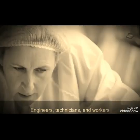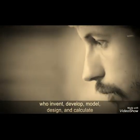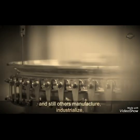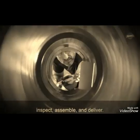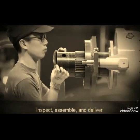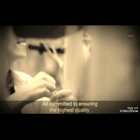The manufacturing of 3D woven carbon fiber composites starts with the selection of high-quality carbon fibers. These fibers are lightweight and have exceptional tensile strength. They are then woven into complex three-dimensional structures using specialized weaving machines. The 3D woven preforms allow for precise control over the fiber orientation, resulting in composites with enhanced mechanical properties in multiple directions.